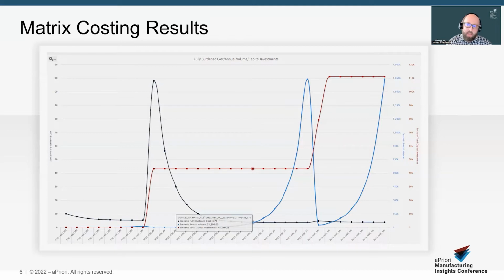As the volume of sheet metal went up, it starts with no tooling, low cost brake press methods. And then once the volumes justify it, it starts getting into some tooled operations, and then all the way up to full progressive die stamping situations.